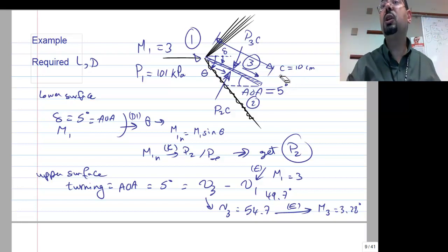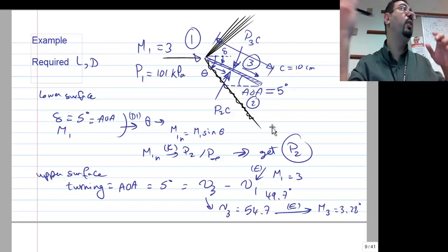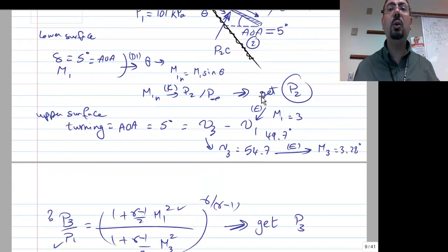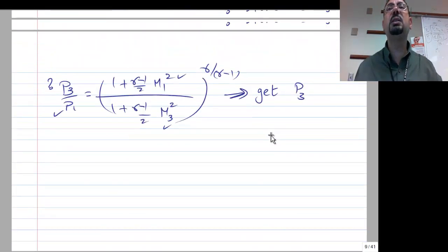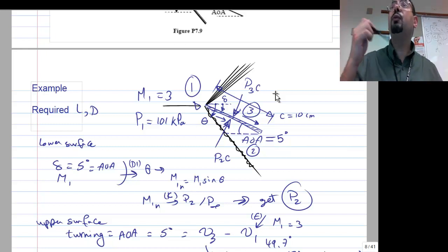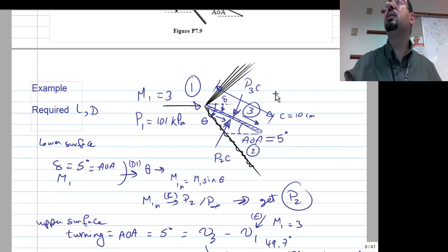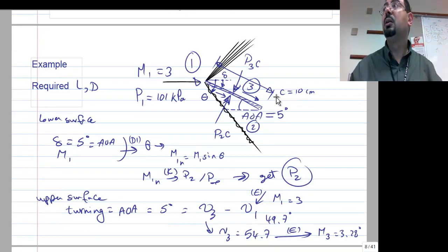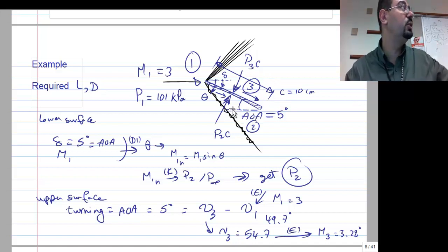Right? So we can actually write it per unit depth. If you only provide a 2D section of the problem, we basically say assuming a unit depth. When you get the pressure force, it's Newton per meter, and that meter means per unit depth. And so the lift force that we'll eventually calculate will also be per unit depth, if he doesn't provide you the depth. Sean: So the pressure per unit area is not the actual lift force yet? Not yet. This is just the pressure force. We'll do the lift in the next page.